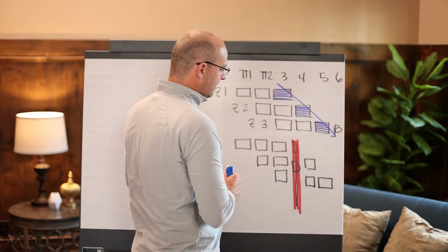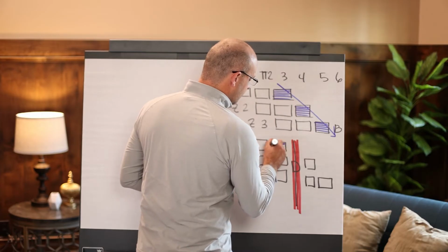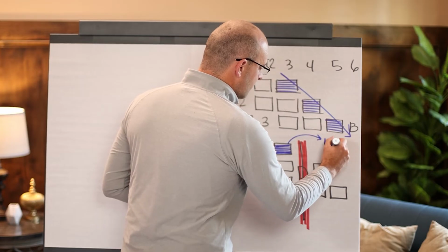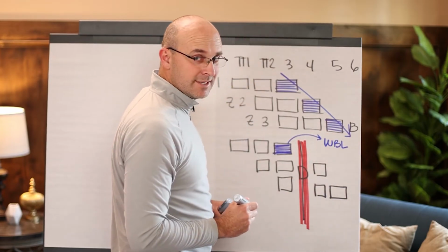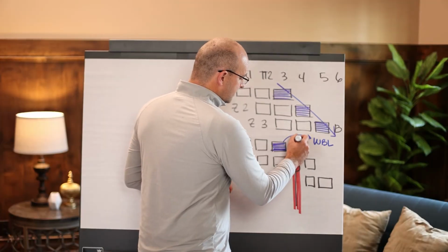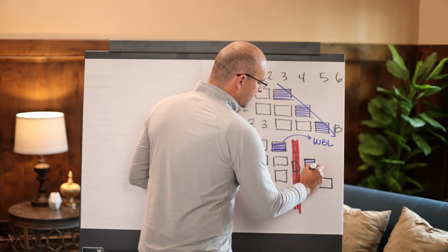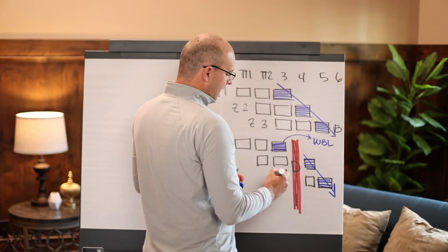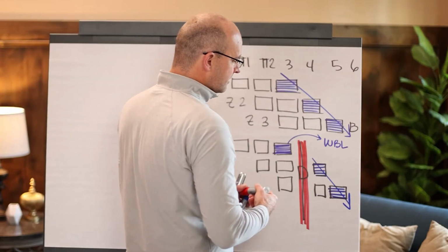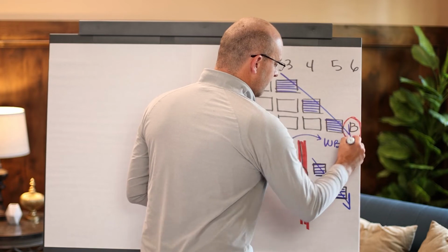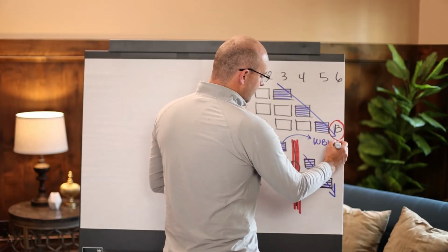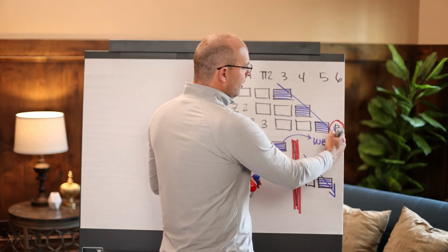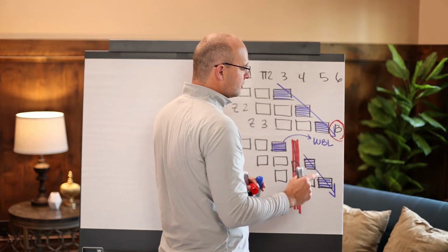So if you have a delay and this trade was working and they started out, you can stop them and ask them to go work on what's called workable backlog, which we've talked about before in the last planner video. And then you can experience that delay and then start them again at the same line of balance, at the same production with the same trade flow. And the key to this is, the only way that's possible is if you eat into this buffer. Meaning that if you shift this over to the right, that buffer is now gone because this activity has taken its place. So now you can see why having buffers in the schedule is so crucial and so critical.